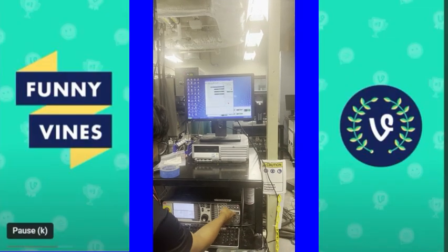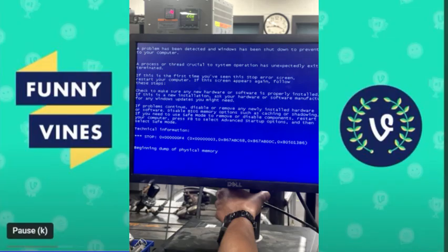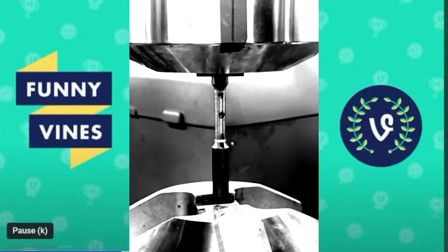The laser extensometer was lined up so that it was centered on the sample and read approximately 2 inches. Some parameters were set up in the MTS program. Due to some technical difficulties, our steel sample was left trapped in the machine for an extended period of time. Once resolved, the sample was slightly pre-tensioned by manually controlling the machine with the program.